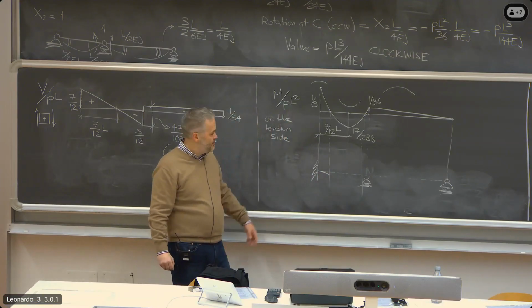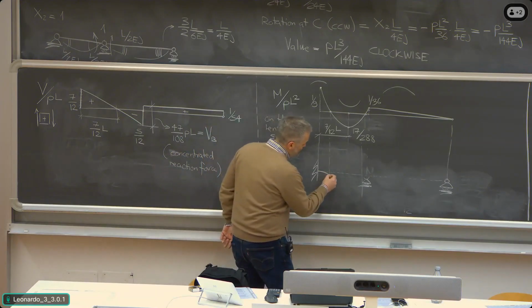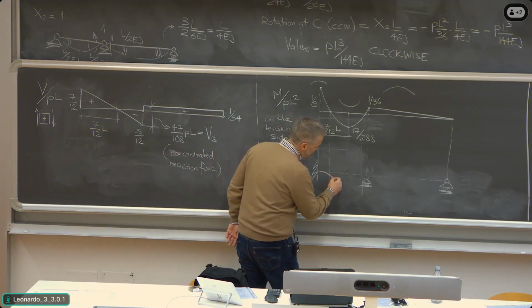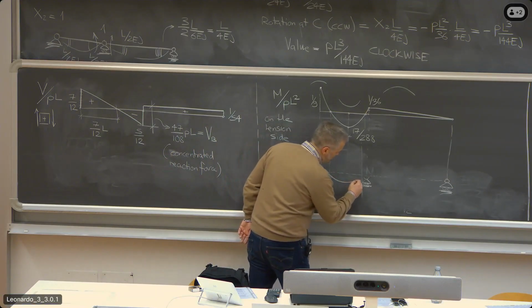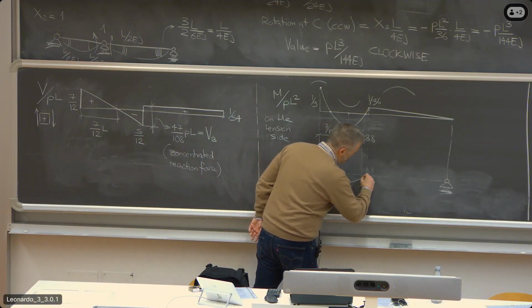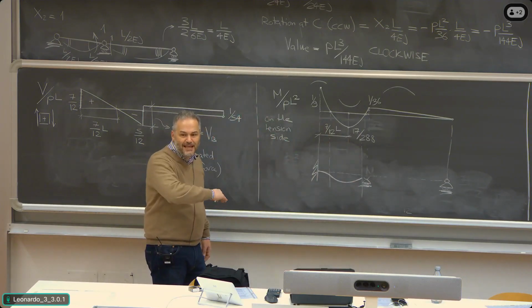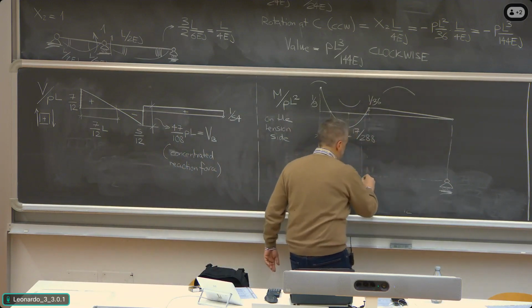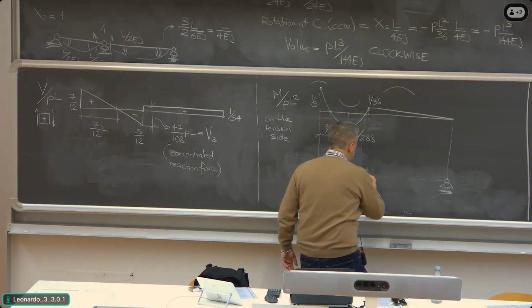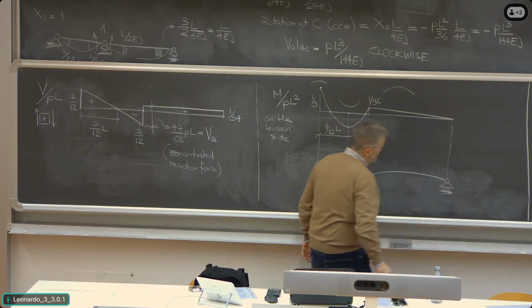Okay? Like a small cantilever. Then change of curvature, which means like this. No kinks in the deformed shape. Up to this point where there is contraflexure, which means again a change in curvature, and then a curvature like this all over the place, passing through point B, which is a support, and going to point C, which is again a support.